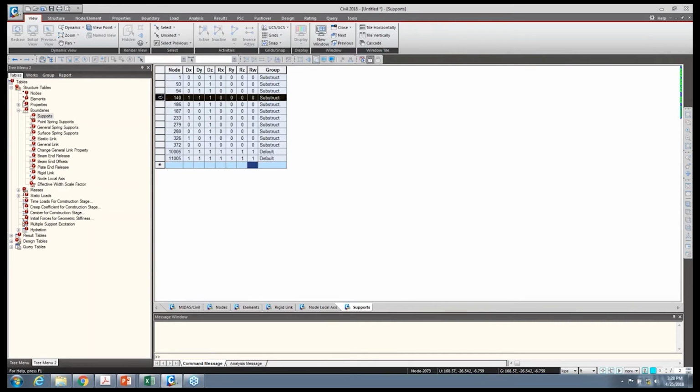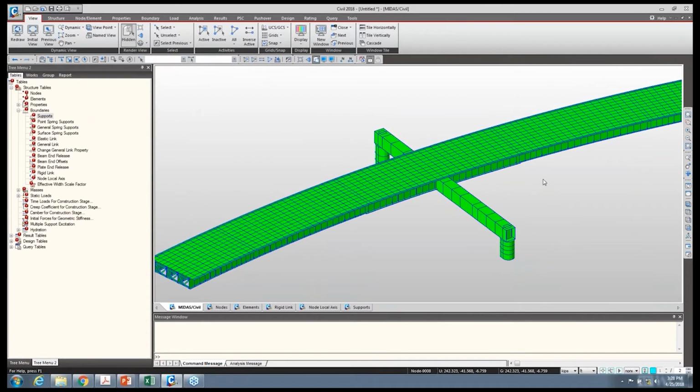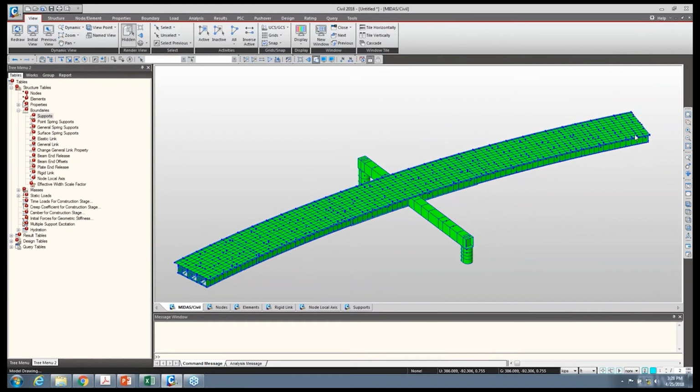the live load. As I previously stated, there's kind of two ways to look at this deck. They either do a frame model or a plate model. What MIDAS does is apply traffic surface lanes when plate elements are used to create an influence surface, and it's going to use this influence surface to then place vehicles. When you're using a frame analysis, the traffic lane lines are used to create an influence line, which is then used to place the vehicles.